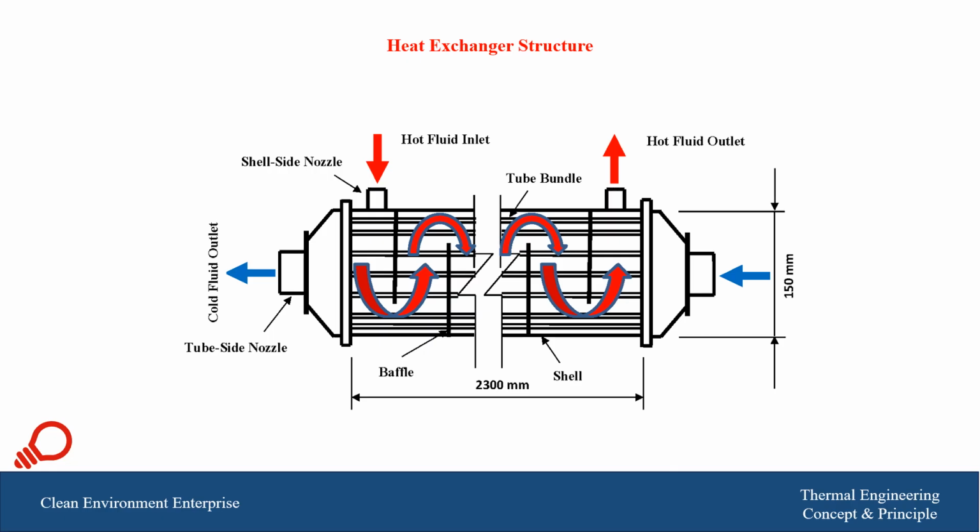And we have on the shell side the red arrow direction, and we may see that the fluid on the shell side, having these curved arrows, passes between the baffles and then leaves at the right hand side of the heat exchanger. And in this way, we have a counterflow between these two streams.